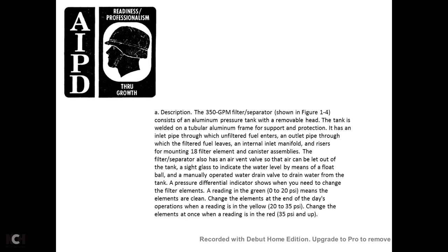The filter separator also has an air vent so that air can be let out of the tank. The sight glass indicates the water level by means of a float with a ball. A manually operated water drain valve drains water from the tank.